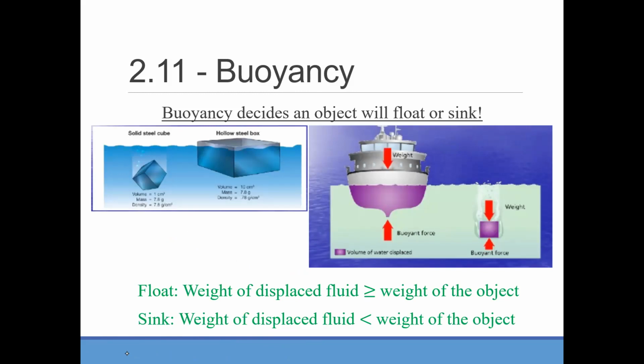Okay, you can see that in these two examples here. One very common example is a piece of steel that will sink, but a big object made of steel will still float because of this concept. When any object displaces fluid, if the weight of that displaced fluid is greater than the weight of the object, it will float.